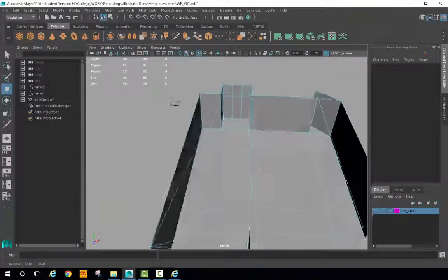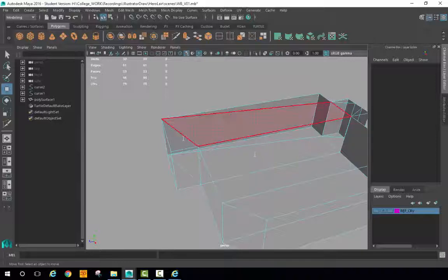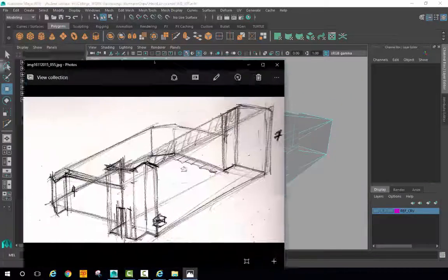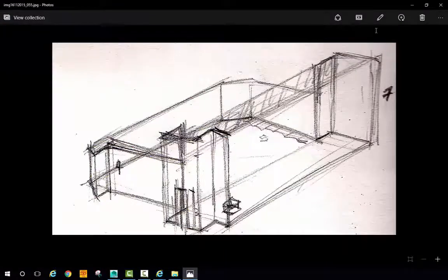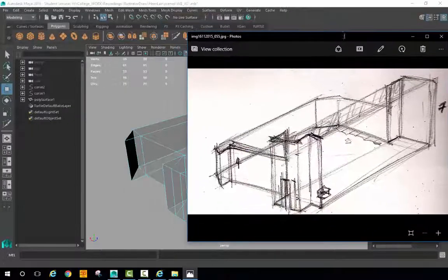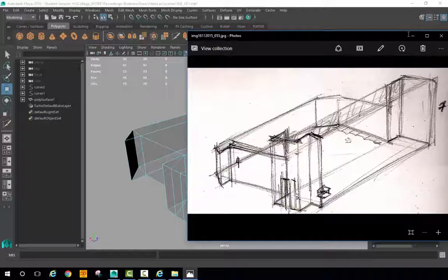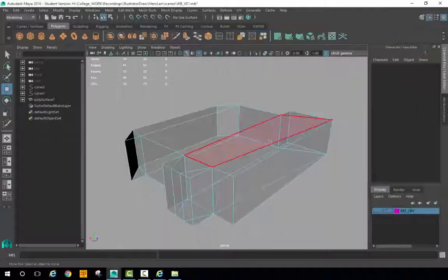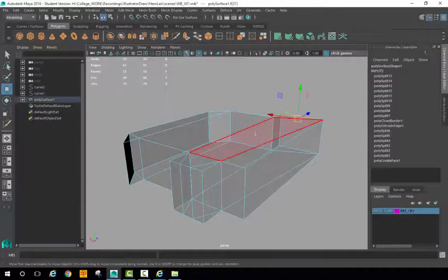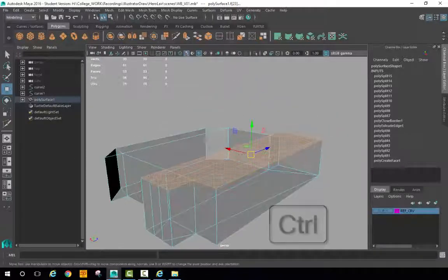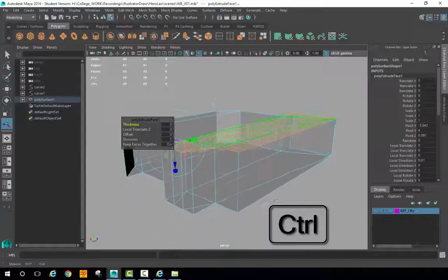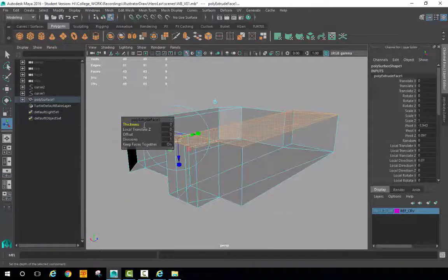and on my drawing that I've been looking into, this is what we're looking at. So I need to extend this up a little bit, so I think this is going up to 7 meters, so I need to add a couple of meters on top, and I'll do that with an extrude. And obviously the thickness on this one is actually going to go the opposite way, so it's going to be a minus. And we're already 4 meters high, so 300.